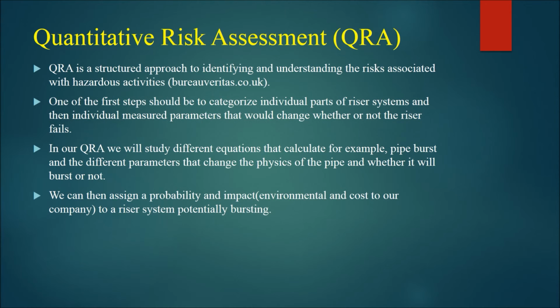A QRA may be a requirement of legislation and/or internal company governance to show that risks are identified and controlled to an acceptable level. The criteria for risk acceptability may be defined by local regulations and/or company investment policy. Typically, a QRA can be defined as the formal and systematic approach of identifying potentially hazardous events, estimating the likelihood and consequences of those events, and expressing the results as risks to people, the environment, or the business.